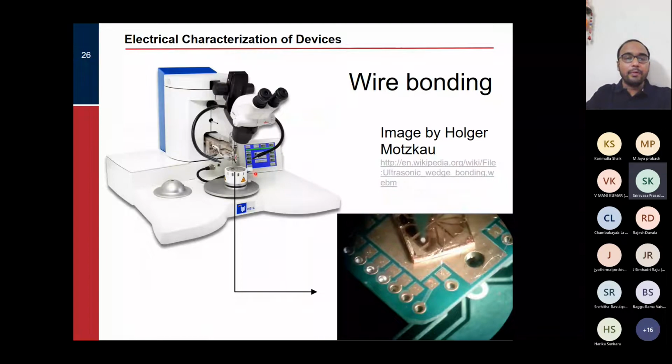If you want to do that, then you can use something like a wire bonder. Basically, an entire roll of aluminum wire is placed inside this, and this is a stitching needle. Now, this is an optical microscope. Let's say your device is kept here, and then you bring this thing here, and you can visualize it at a large magnified version from this point.